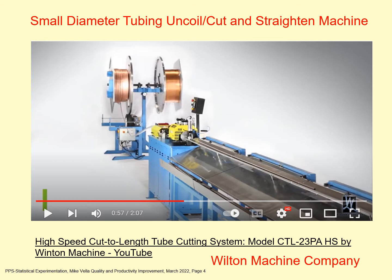The tubing then advances or is pulled by what is inside that first yellow box. Those will be typically the pulling rolls, or they might be considered pushing rolls. And then it goes through a straightening operation and a cutting operation, which is found in that second yellow box. The tubes then are formed into cut lengths, and they are straightened and they roll down that trough to be entered into the next process.